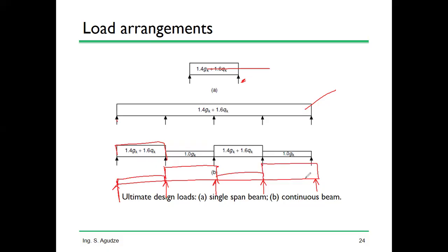And look, analysis or design is iterative. So for example, this will be A, this will be B, this will be C. So we have to analyze all of these. Then I'll look at case A, B, C, D. If I'm looking for shear force, where did I have the biggest value for shear force? I pick the biggest value. Maybe the biggest shear force may be here, or maybe in B. I'll pick it. Then I'll do the bending moment.